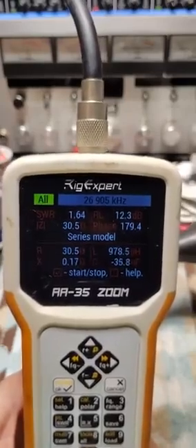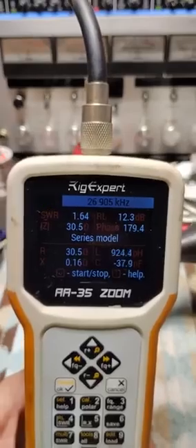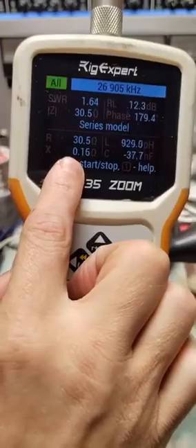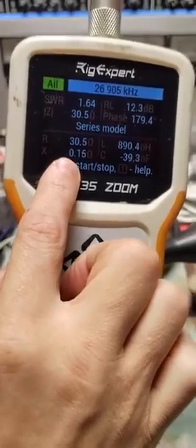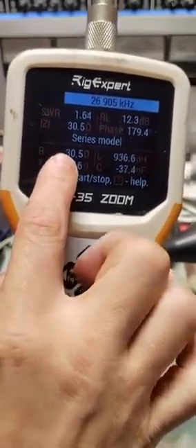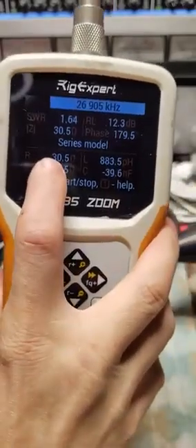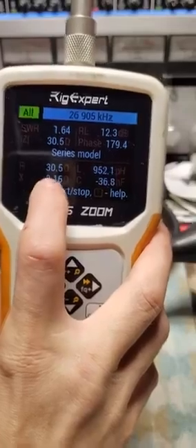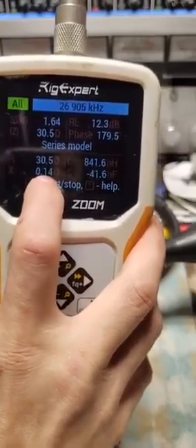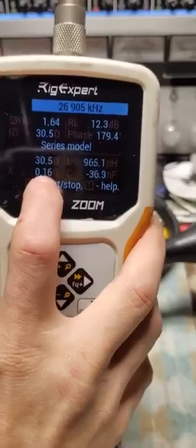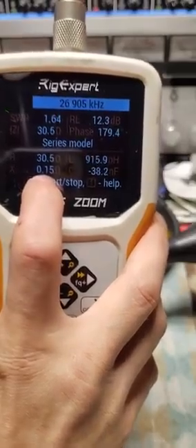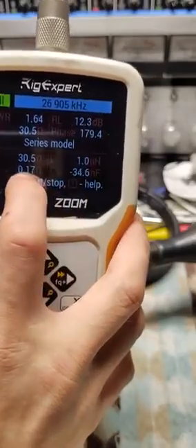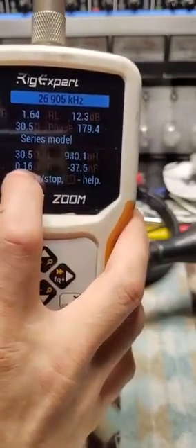So you tune your antenna with a tuned half wavelength piece of cable, and you get the reactance to 0. Whatever the ohms are is what they are. And then you've got a matching network that needs to be tuned. You do your reactance with length, and they all kind of play into each other. But you want the 180 degree phase angle when you're tuning the antenna, and you want to tune for X0 with that half wavelength piece of cable.